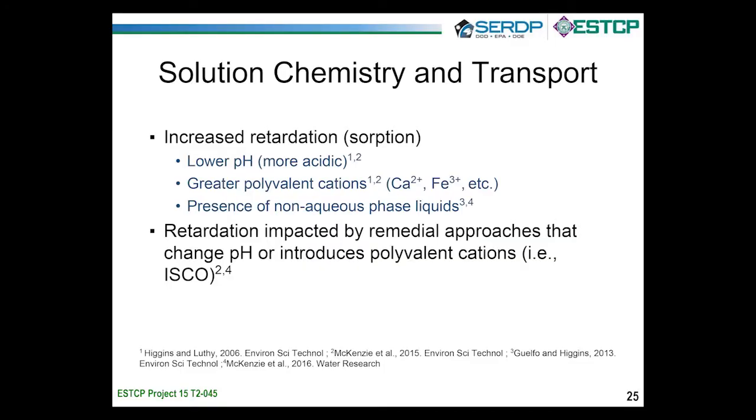There's also some evidence to suggest that these compounds will interact with non-aqueous phase liquids. If there are residual fuels or NAPLs of various sorts present at the site, there's some indication that they will interact, although that is very much dependent on the individual compound as well as the solution chemistry in the system. And the important thing here is that if any sort of remedial technology has been employed at a site that would change the solution chemistry or the solid phase chemistry, that has the potential to change the retardation of these compounds. So if you employ ISCO, or in situ chemical oxidation, that dramatically lowers the pH or increases the amount of polyvalent cations, you could expect greater retardation of these compounds in those systems.